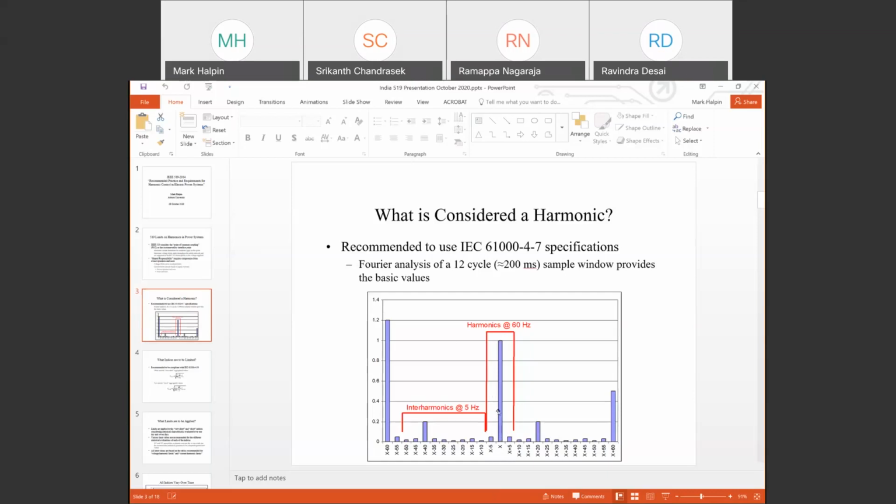And that's important because, especially in the case of actual harmonic distortion, it's not a stationary phenomenon, which means that the digital Fourier analysis will not be perfect. There will always be some content scattered throughout the spectrum. So those plus or minus 5 hertz terms are not necessarily insignificant, and it's important to realize that needs to be taken into account.